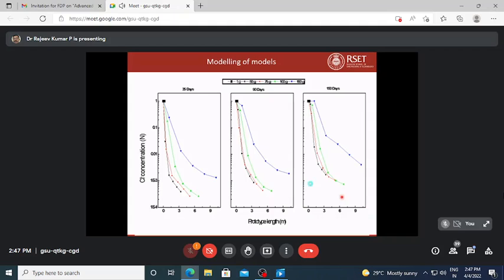And to make sure that the centrifuge modeling is correct, one can go for modeling of models. At different acceleration levels, you get almost similar values. It means that your modeling results are correct. This was developed by other researchers also. For this experimentation program, we received a very promising answer. You can see the higher acceleration level values are slightly away from the other three.